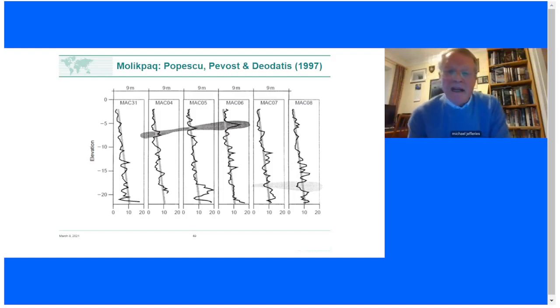Well, back to the Mildred-Lake pack. What we did on the pack, we actually took an interest in this issue of soil variability. And we started playing with spacing of the CPT to try and chase down how continuous were loose pockets and how continuous were dense pockets. And you'll see on the top of the diagram, we actually brought the spacing down to 9 meters before we could reliably start seeing how loose zones and dense zones merged into each other. You can see they're highlighted in dark gray is a dense zone, and down the bottom right, there's a loose zone.